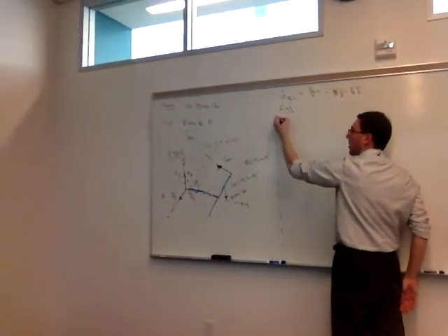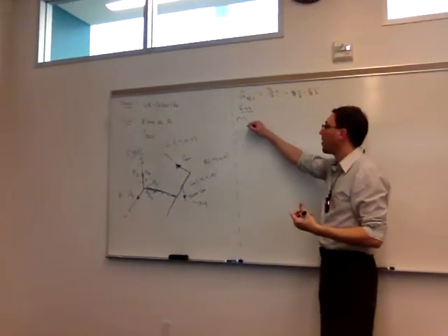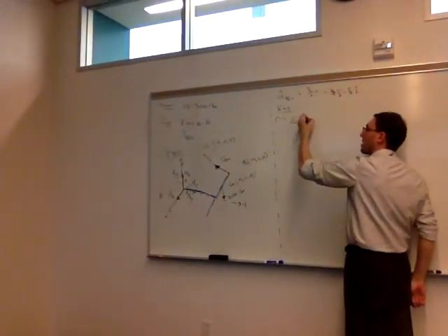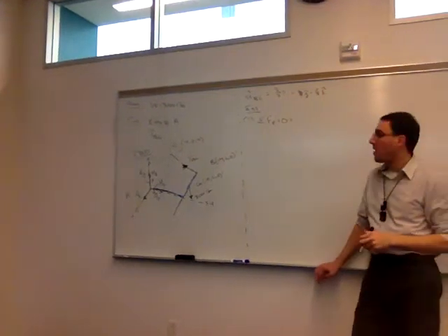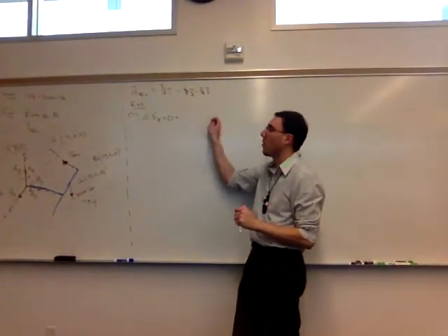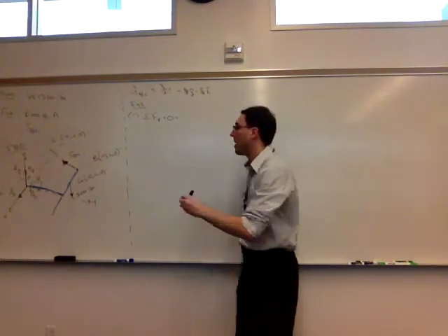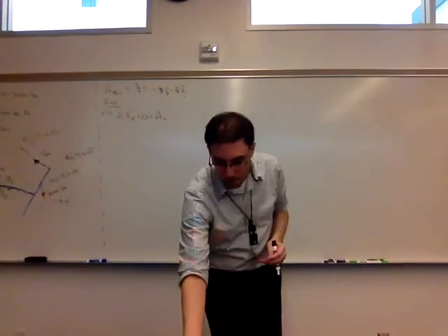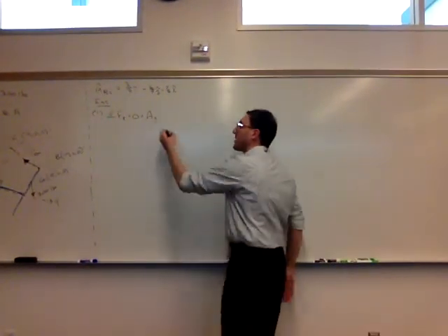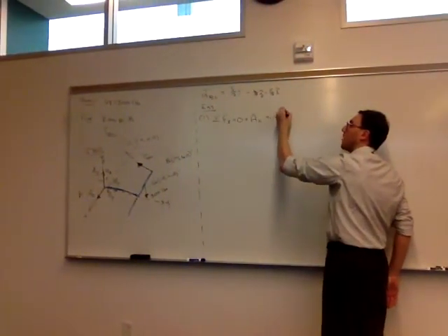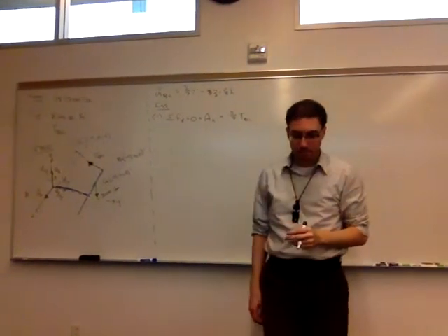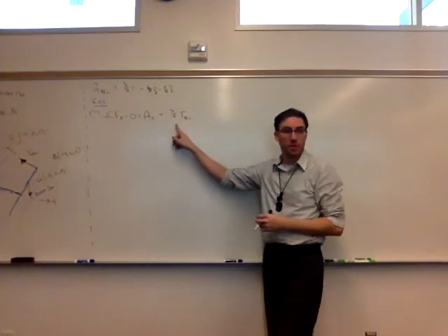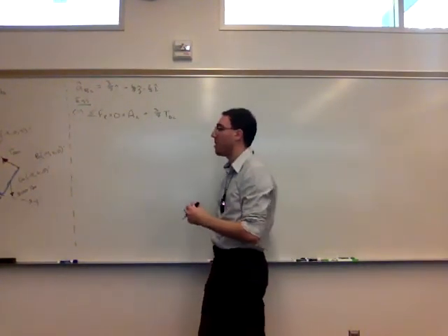All right, now I'm ready for equilibrium equations. Again, 6 of them we're going to get, so labeling them, numbering them is really crucial to keep track. All right, so we'll start with our friend the x direction. So what's our right-hand side here? What forces are in the x direction? Right, so all of Ax. Right, so the i component or the x component of TBC, so the 3/7, and we don't know its value, so 3/7 TBC. Right, and those are the only things in the x direction. So we have 1 equation, we have 2 unknowns so far. So I'll put it aside for the moment.